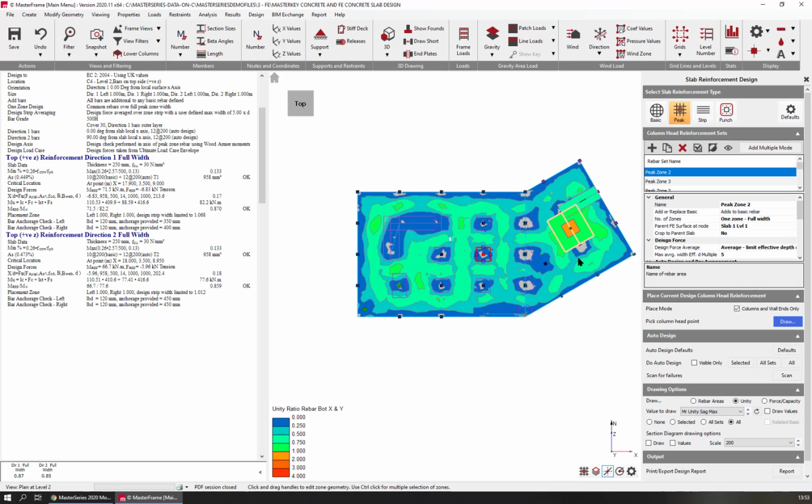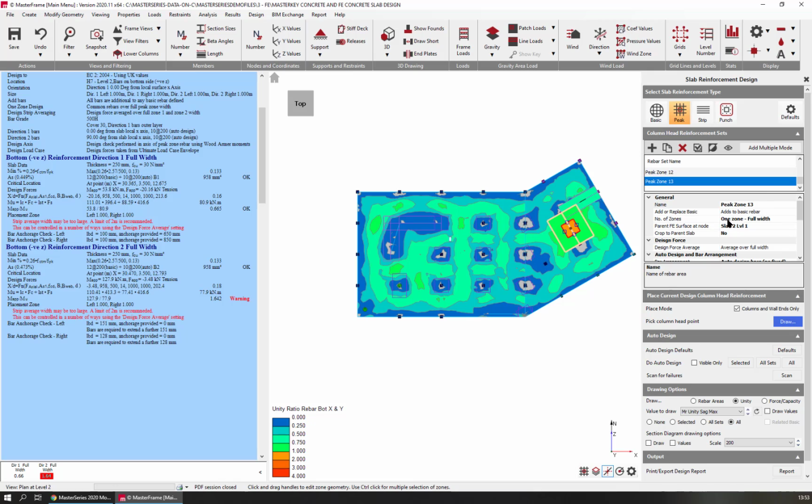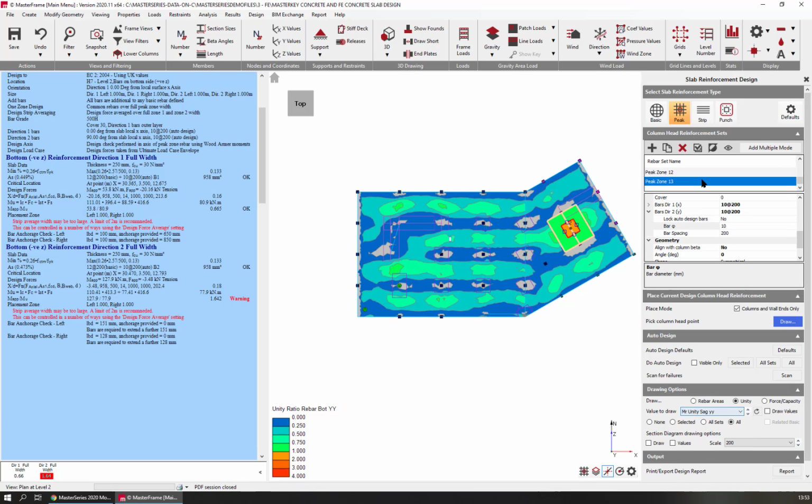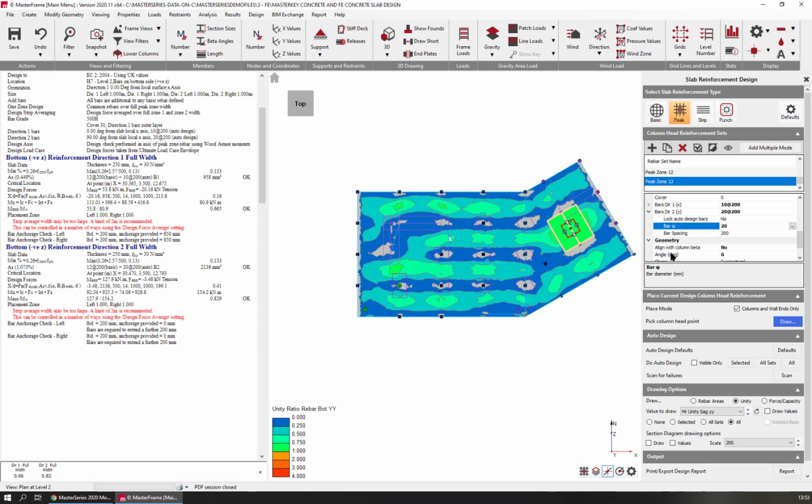So if I went back to that peak, I would have to increase the steel in that direction to be the 20s. So it was in the YY, I think. Well, let's not guess, let's find out which one it is. Is it the Y? It is the Y. So direction 2 YY. Change those to the 20s in there as well. And they're now the same, and it's now harmonized, and it's all very, very good. So that's our design from a main steel point of view.